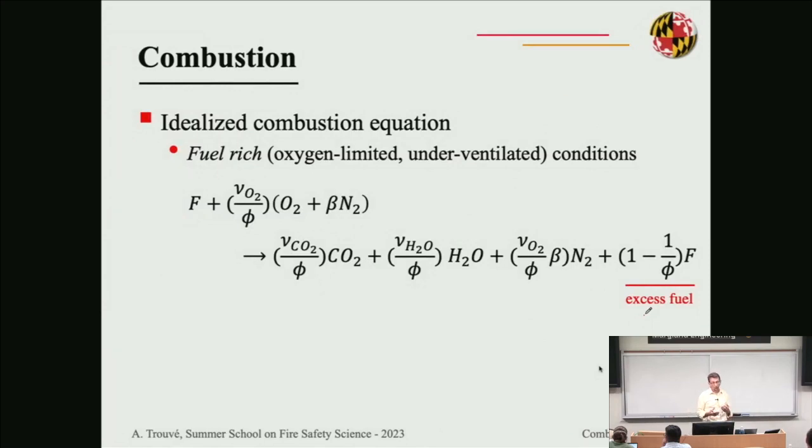So this combustion equation, again, can be adapted. Usually it's written in textbooks for stoichiometric conditions, but you can extend it and apply it to this fuel-rich regime and describe that way the effect of under or overventilation.